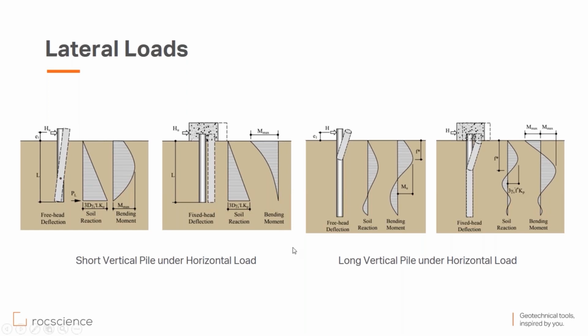We may also need rotation or lateral displacement or vertical displacement of the pile. And of course, any other structural requirement like stiffnesses, like soil reactions. RSPile, as a software for a piling engineer, can handle all these requirements.